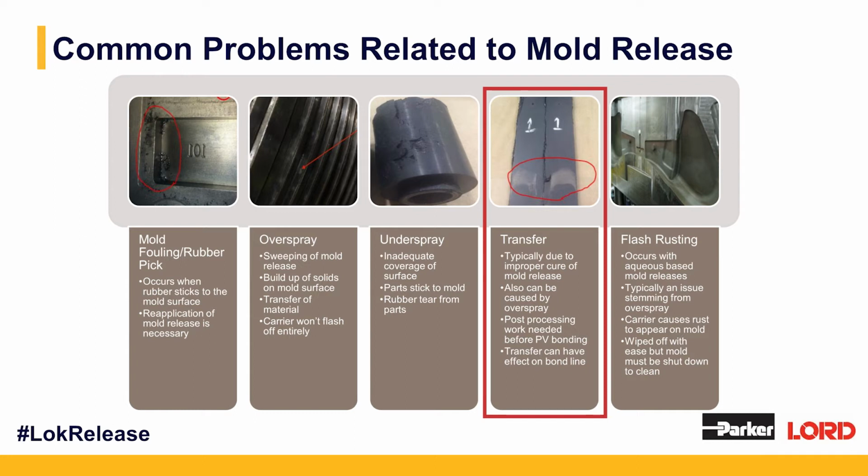Special cleaning operations are required if any mold release transfers to the part when you have these secondary post bond operations as part of your process. Those secondary cleaning operations can be quite lengthy and cause a lot of downtime. So it's best to make sure you apply the mold release at the right level so that it doesn't transfer